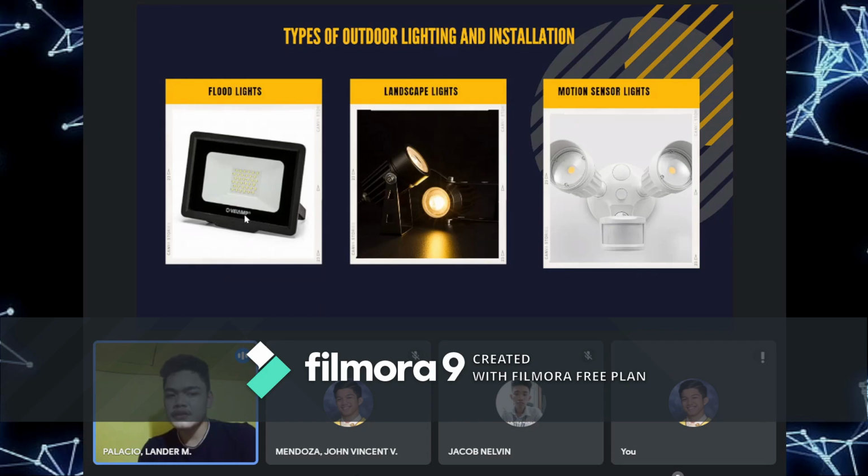And what are the considerations naman? Or what are the tips para sa improvement natin? So according sa PEC2, select your location and identify a nearby power source bago tayo mag-install ng floodlights. And then make sure natin that we have a safe way to access the installation location, and then cut a hole to fix the fixtures and run electrical wire through it. Connect the fixture to a power source and test the lights and features. And then kapag meron tayong problema, make adjustments accordingly.